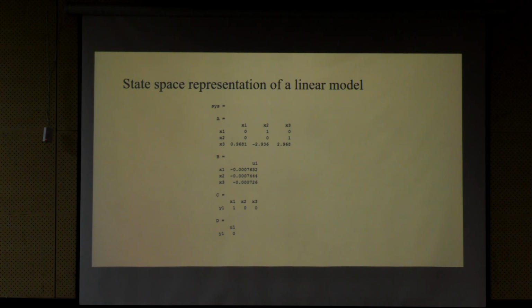Then we will see how the input and output are linked. So the plant model is going to give you the relations between the input and output. Then we will linearize the model and we will get the state space representation like this. Once this is done, we will open the MPC designer.